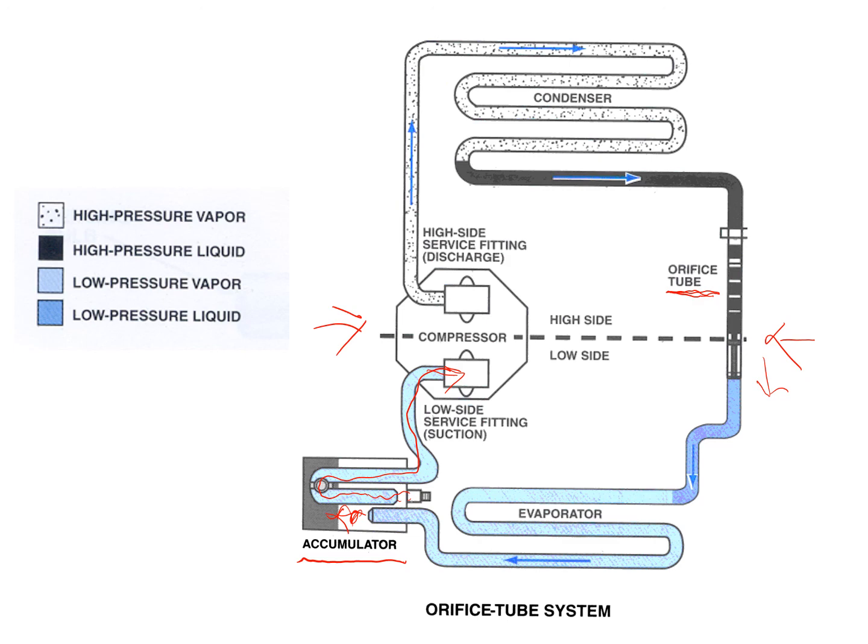Again, the orifice tube can't be adjusted in a fixed orifice tube system. So where it's not adjustable, there is a chance under certain atmospheric conditions and temperatures that the refrigerant may not all vaporize.